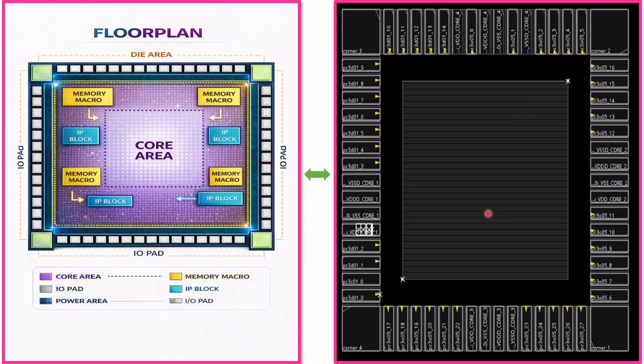And the next important thing is that major blocks like SRAM, hard IPs, ROM, and PLL must be placed properly in the earlier stage itself, because it is difficult to move those in the later stage. So the planning of this must be proper. If they are not placed properly, they create routing blockages and they affect the timing heavily. So placement is very important.